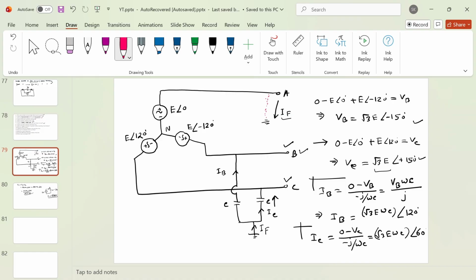So even though you have removed the faulty object, because of this ionization of the path, you will still see an arc. The arc will still be visible. Even though you have removed the fault, the arc will come and go like that. That happens because of this ionization.